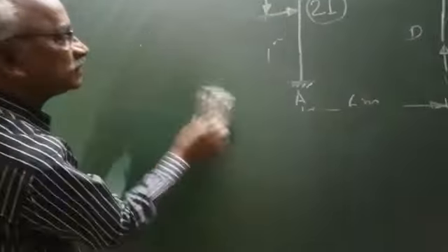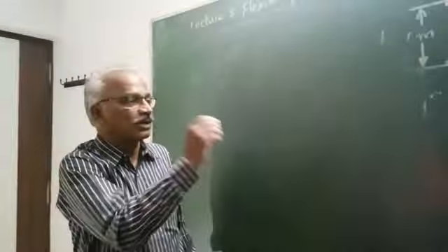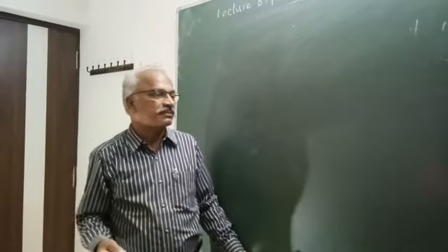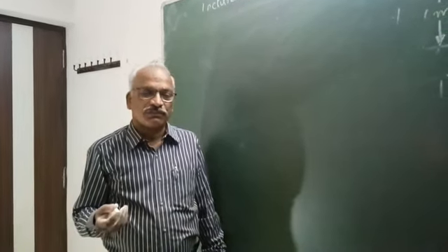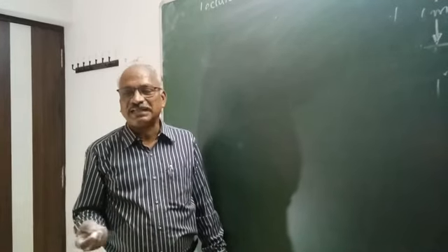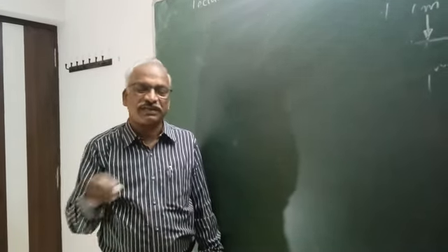So we have covered two frames. One is symmetrical, the other one is unsymmetrical. We have covered two problems. One is with the static indeterminacy 3, the second one is with the static indeterminacy 2. That will give you an idea, because when you choose a problem with the static indeterminacy 3, we have to form the A0 matrix, which will be of size 3 by 3, and invert it.